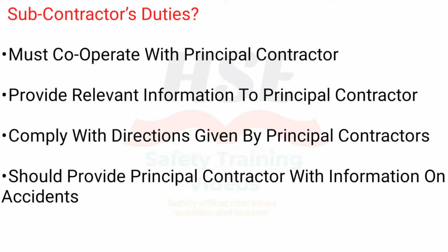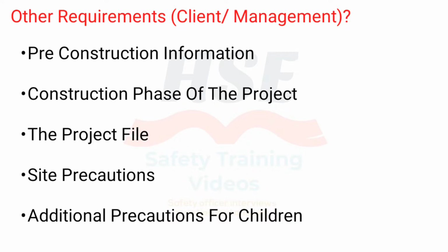Subcontractors' duties. Must cooperate with the principal contractor. Provide relevant information to the principal contractor. Comply with directions given by the principal contractor. Should provide the principal contractor with information on accidents. Other requirements, client and management.